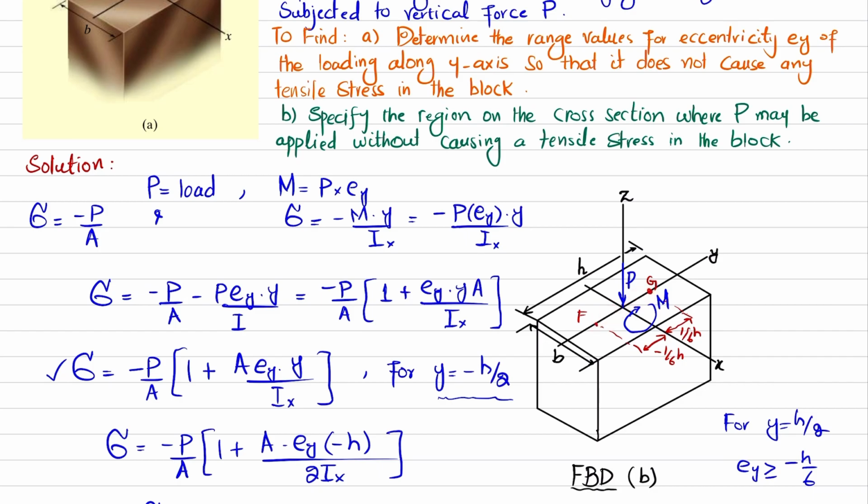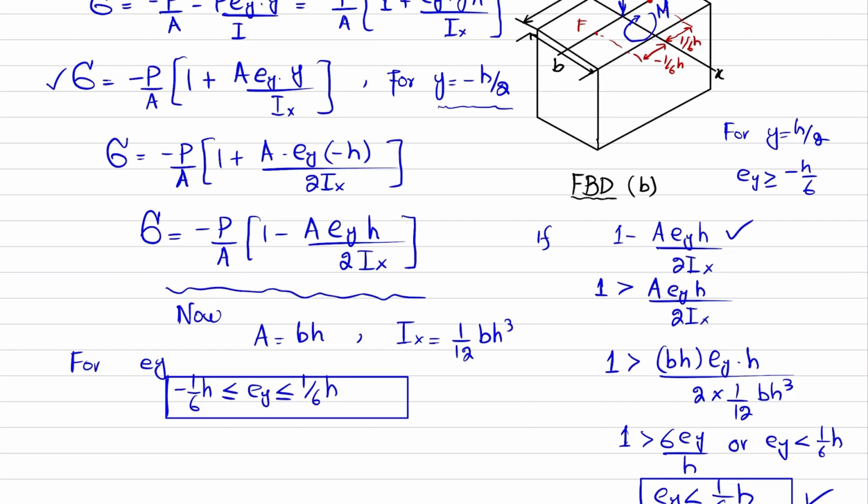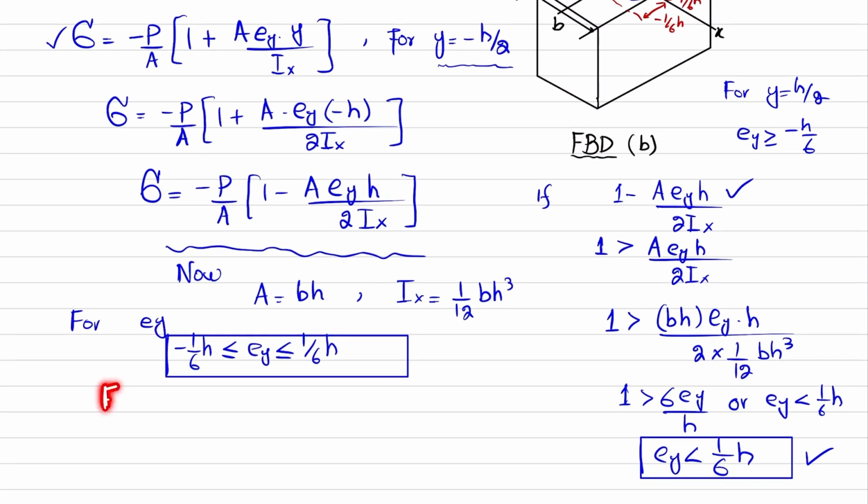What about this width b? Note that this is sometimes referred to as the middle third rule. What does it say? It is very important to keep this rule in mind when loading columns or arches having a rectangular cross section and made of material such as stone or concrete, because they are good in compression and support little or no tensile stress.